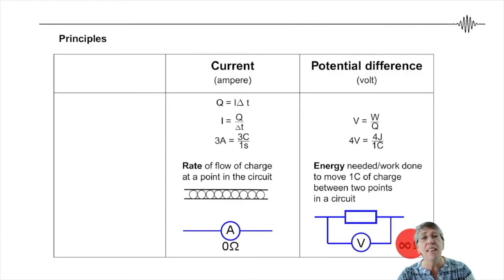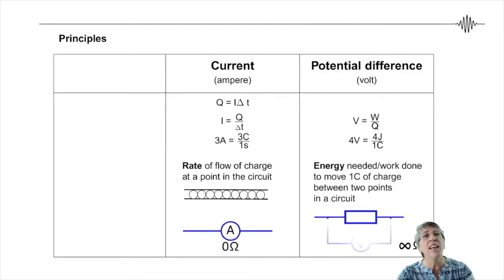So a voltmeter has an infinitely or a very big resistance, which means when the charges arrive over there, nothing will choose the bottom path because the resistance is too big. Every single charge will pass through the top. Right, guys, and that gives us a way to work with voltmeters. If there's a voltmeter in the circuit and you are confused because it's very busy, you can ignore that voltmeter because no charge is traveling through that voltmeter.